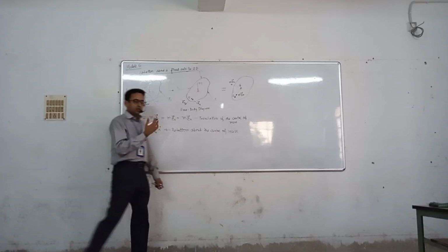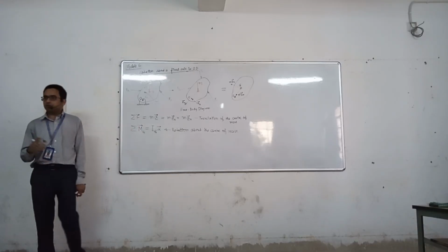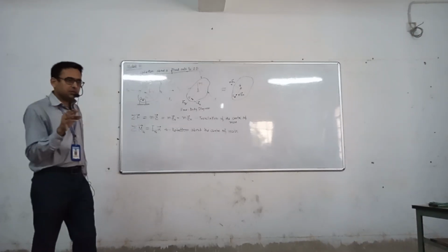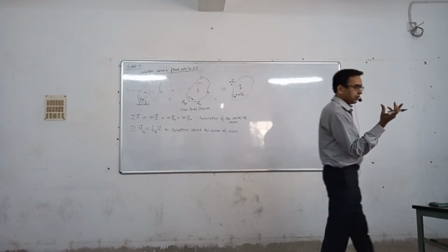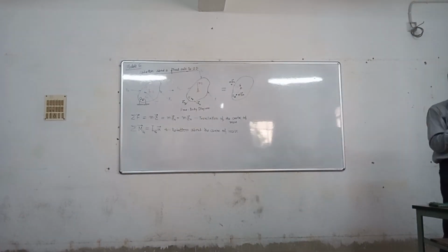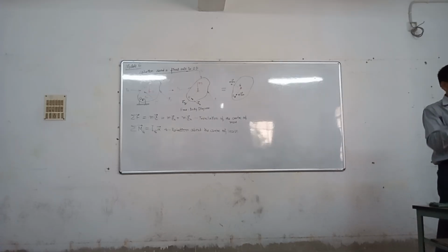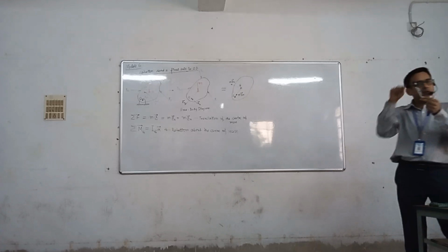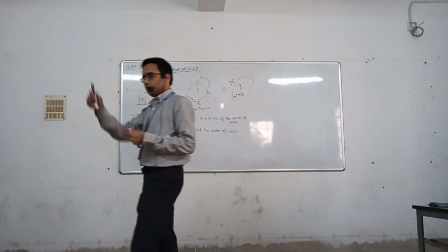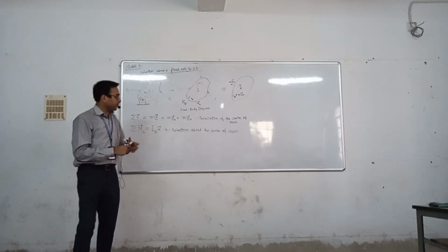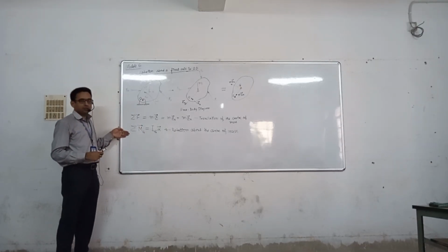Okay, these two equations simultaneously, because for a rigid body, when it is subjected to forces, it will not only be translating, it will be rotating, right? Because at different points you may have different velocities. For a translation, all the points have the same velocity. But for a rigid body, all the points may have different velocities. Therefore, it will be rotating and translating at the same time. So since both are happening simultaneously, both equations are available this way.